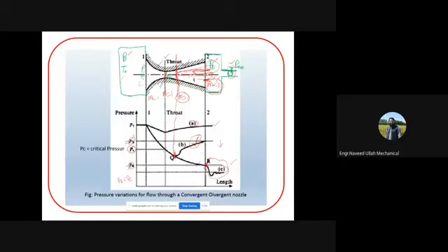And if it is out of the nozzle, then actually it cannot harm us, right? So for that reason, relocating this shock wave out of the nozzle, there is a specific back pressure value. And if you obtain that back pressure value, at the exit you will be having maximum jet velocity and maximum mass flow rate, and that is the requirement, if you remember. Ahead in jet propulsion we will see why we want to increase this mass flow rate and jet velocity. I hope you understand. Okay,